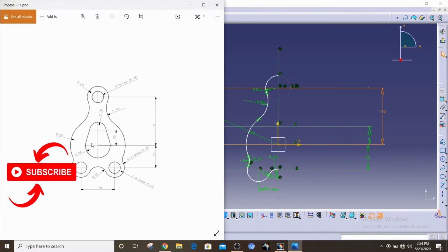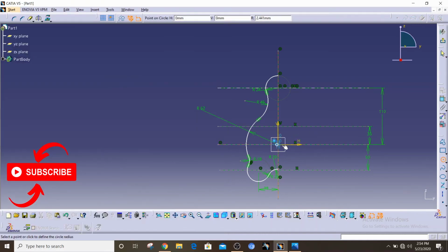So now what's left is this thing here. So this is basically one circular arc here, the top circular arc, with two bitangent lines joining them together. So I'm gonna make, oops, sorry, this has to be on the origin, first one, the second, oops, it has to be, there you go, second one, just make sure they're coincident, yep, and this one as well.